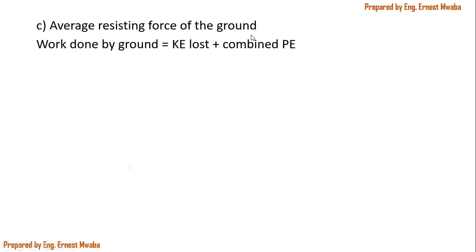Remembering that this is actually going to penetrate the ground by some distance, meaning that there's also going to be some loss in potential energy. Then one other thing is that when penetrating the ground, it is a combined mass of both the hammer and the pile that is actually at play. So we have to ensure that we use that velocity, that kinetic energy with which this unit penetrates the ground.